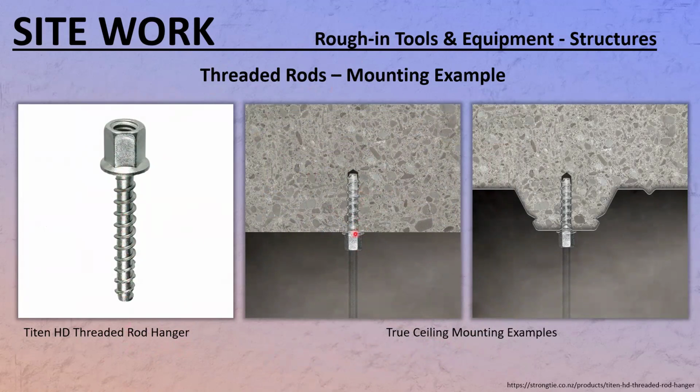You drive into concrete. Well, first you need to drill a hole with the hammer drill. The hole is supposed to be the size that's specified when you buy those. They're going to have that in the packaging, what size of drill bit to use and how deep to drive it in. You drive that into the concrete, and if it's properly done, it can handle a lot of weight.